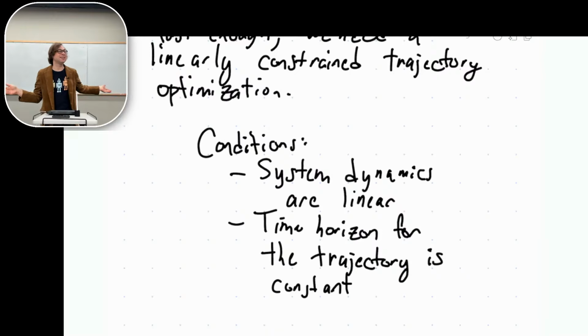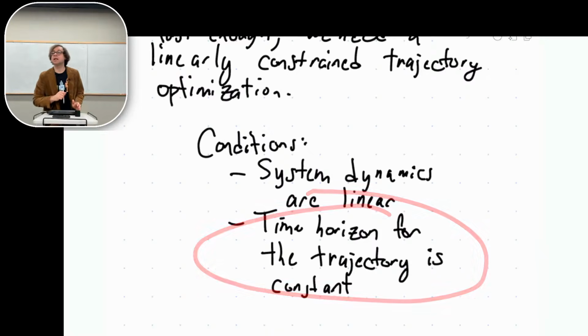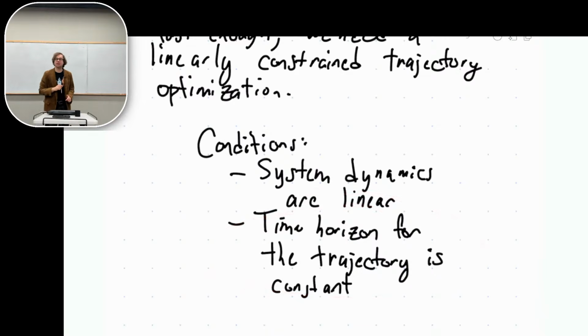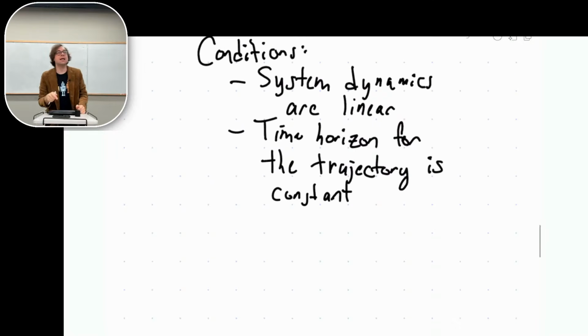Minimize time, right? So the time duration was a variable in our decision vector. It's something we could change. In MPC, to get your linear constraints, you have to give it a constant. It's very typical to give it a constant time horizon. And you can see that in the video. If you look at the length of that line that the drones were thinking through, that was a constant time into the future it was looking at. So when the line was non-existent, it just predicted it was going to stay in place.